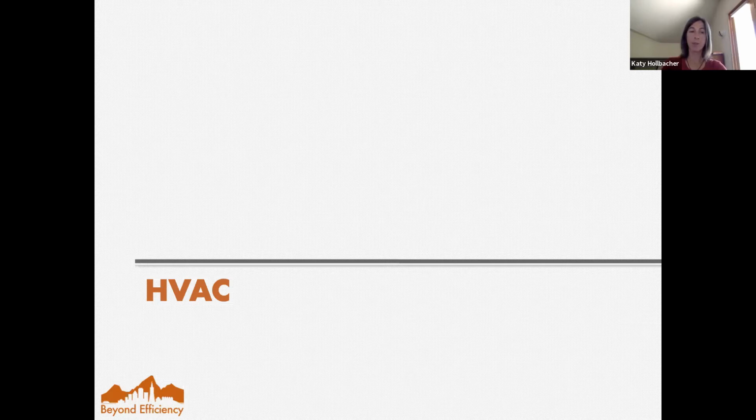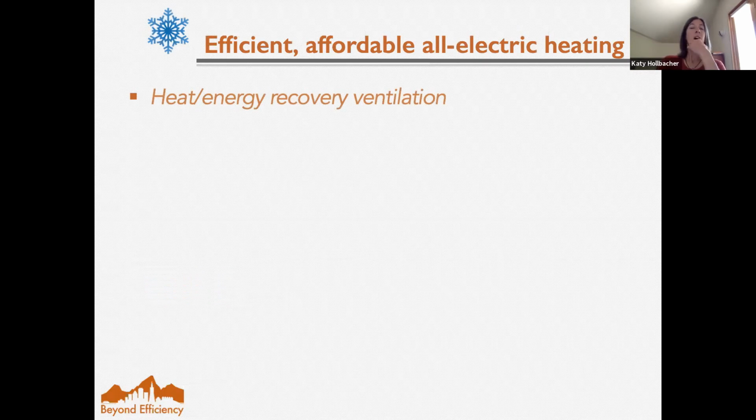You just have to know what the limitations of this equipment are and know how to integrate backup systems when a piece of equipment can't operate at, say, -10, and know that on the net annual balance, if a piece of heat pump equipment is still operating in heat pump mode, you're still significantly improving the energy efficiency and reducing energy use for a property.